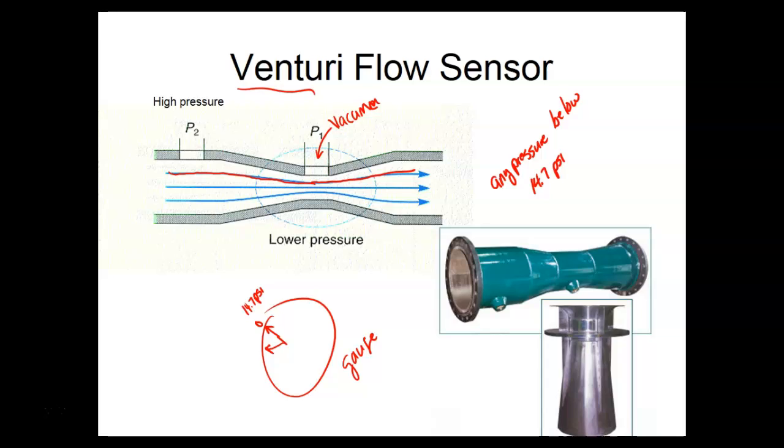Both of our suction cups over on the Festo line and also on the Amatro line use this technique. They just don't have this part right here. It pushes air through a Venturi, which makes the pressure less than 14.7 psi. We've got a little suction cup out here. This side is below 14.7 psi, and out here, where my plate is, the pressure is greater than 14.7 psi.